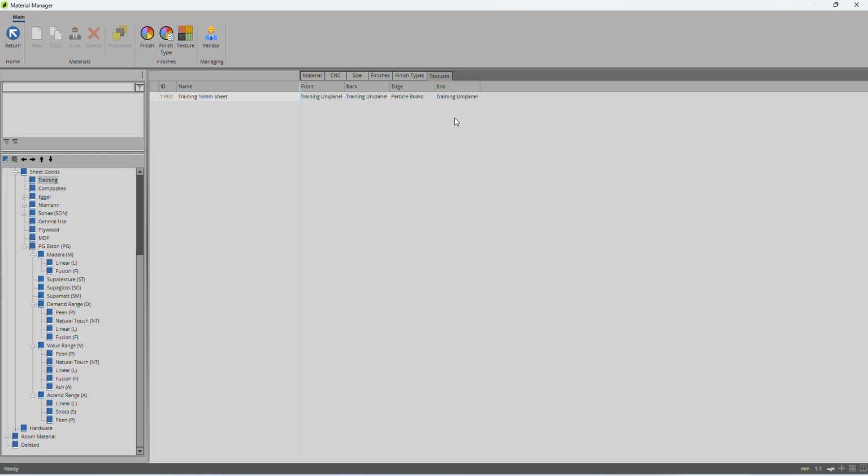And in this case, where we selected our board and you want the edge, front, and back in the same color, can you choose it to be single face? That we do with the construction method. Okay, so this is just the material. Just the material. Yeah. So once we created the material, we're going to assign it to a material schedule, and then the construction method controls what the material schedule does. Sure. So you'll be able to tell, in the material schedule, you have a front edging, an exterior edging and an interior edging. So exterior will always be your colored board and interior will always be your carcass color edge. So in your construction method, on all of your parts, it's going to ask you where you want to edge, and you want to edge with exterior or interior. And then you just decide.